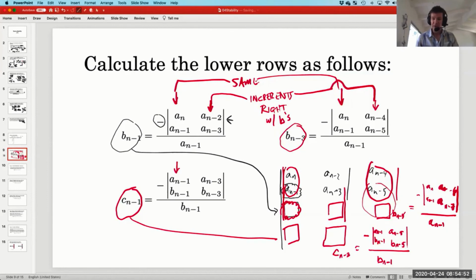There was a question, does stability always describe poles in the left half plane, or is it based on the closed loop transfer function? So let's take a second and consider, what does it mean to be a pole? It means to be a root of the denominator of the closed loop transfer function. So I think the answer is it's not an either or proposition. You have to find the poles by looking at the roots of the denominator of the closed loop transfer function. And if those roots are in the left half plane, then the closed loop system is stable. This is the pattern or the algorithm for building the Routh array.